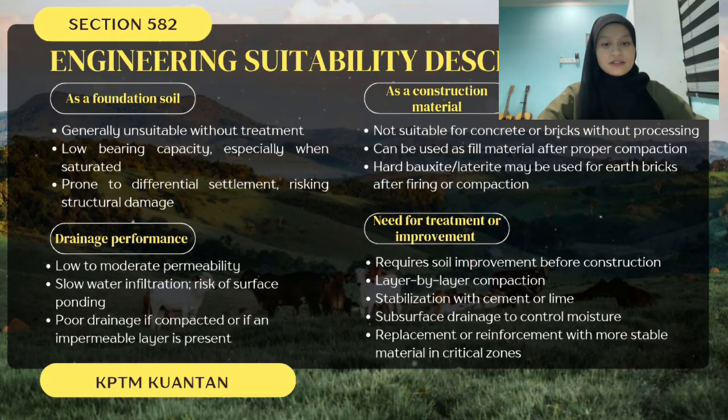Engineering suitability analysis. First, as a foundation soil, bauxite soil is generally not suitable as a foundation material unless properly treated. It has a low bearing capacity, especially when the soil is saturated with water. This makes it prone to differential settlement, which can lead to structural damage over time.